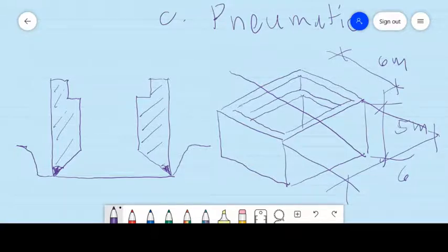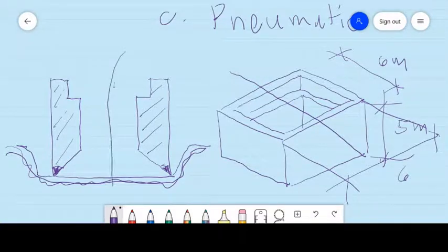Now, the caisson is first cast in place. Through surveying, they determine the exact location and then excavate at the riverbed where to cast it. After casting, the caisson is sunk through gravity, through its own weight, by excavating the soil inside the caisson.